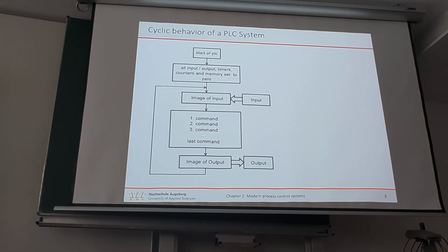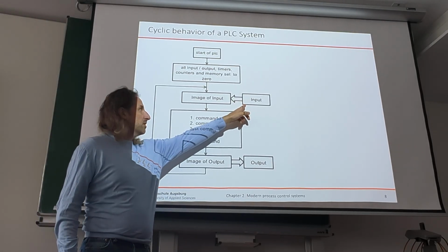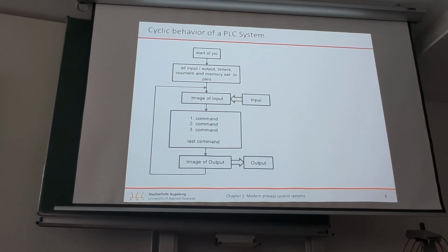So if you read something from the input, it's not the current value, it's the value at the beginning of the PLC cycle. That's what you work on. You only work on the image of inputs, you don't work on the inputs directly. If you are in a microcontroller, you read the register from a pin and you get the current value.